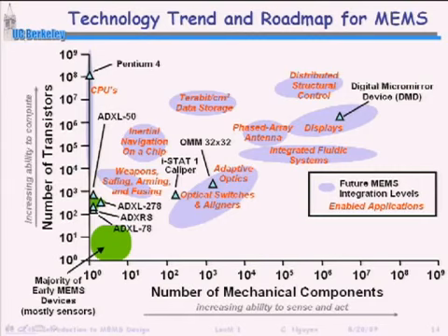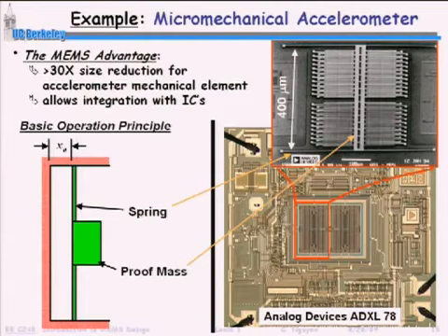So what an accelerometer is, it's a device that detects acceleration. Why is that such a good thing to have? Well, in your Wii device, when you move it like this, right, you need something to detect that you've moved it like that. So something had to detect the acceleration. Something also had to detect which way you're pointing. So not only do you have an accelerometer, but you have a gyroscope in that device. In your automobile, when you crash, what tells the airbag to deploy? You have to have something that says, "Ooh, my acceleration just went to an enormous negative acceleration." And once you hit that negative acceleration threshold, out comes the airbag. Okay, something has to detect the acceleration. It turns out that the devices that detect the acceleration in automobiles are all MEMS devices now.